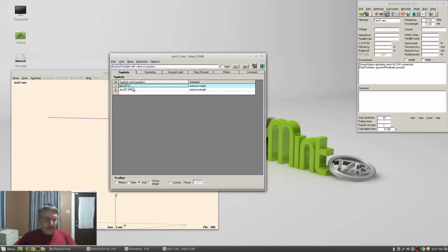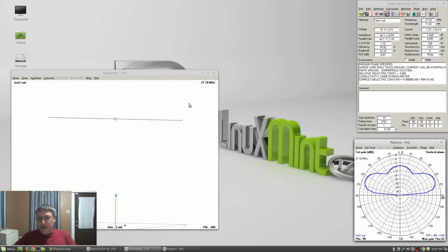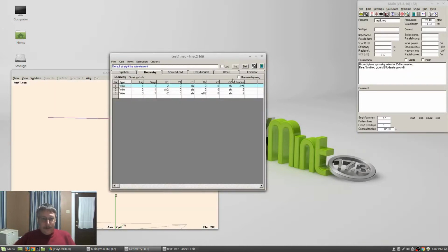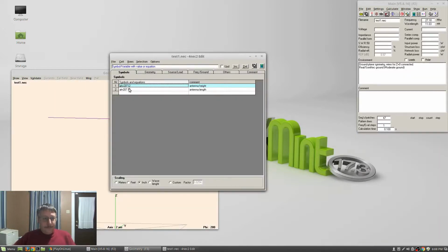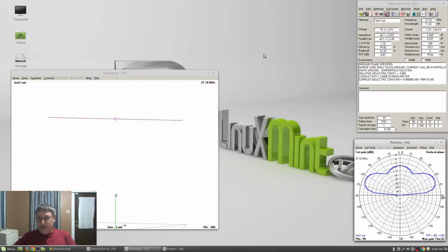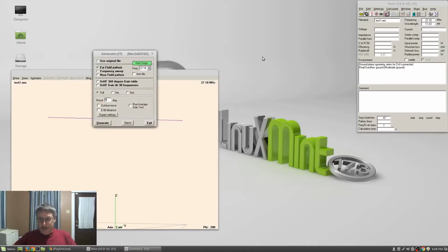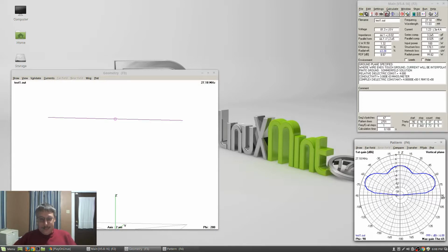Changed. I need to make it slightly longer. Hmm. 947. Just get me close. Come on, get me close, right into that resonance spot. 0.02. Reactance of plus 0.02 isn't going to be that big of a deal.